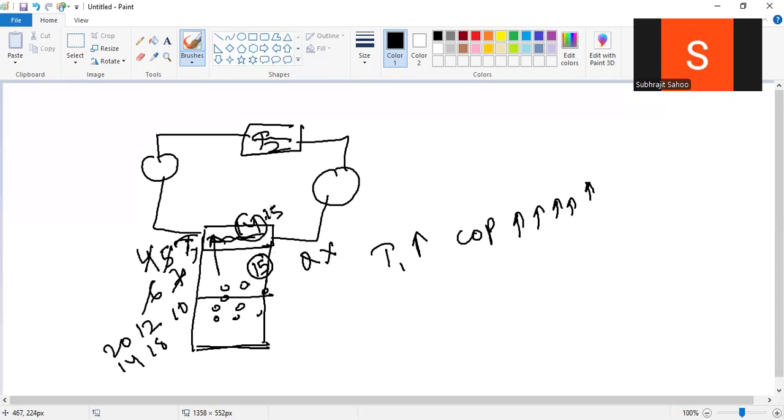Now suppose I increase from 15 to 16 because I want more COP. If I increase T1, I get more COP, as I know from the derivation of the expression. So instead of 15, I kept it at 16. Then T1 temperature is more and the inside temperature is less. So instead of heat extraction, heat will flow in the reverse direction into the refrigerator. Very important point. Observe.